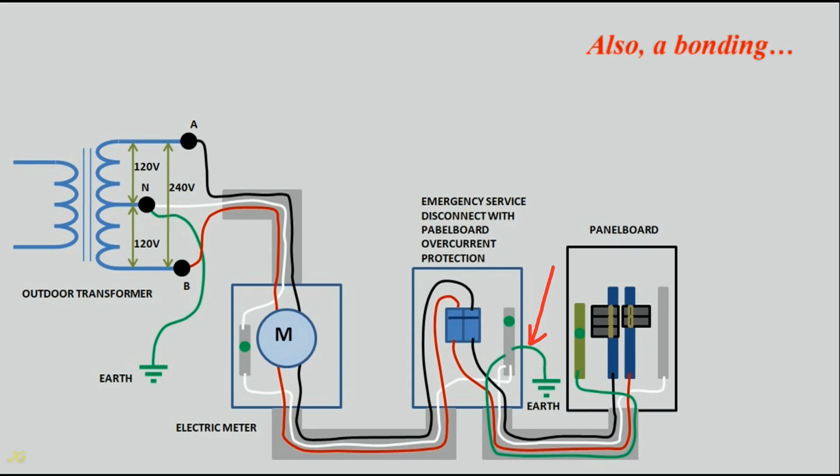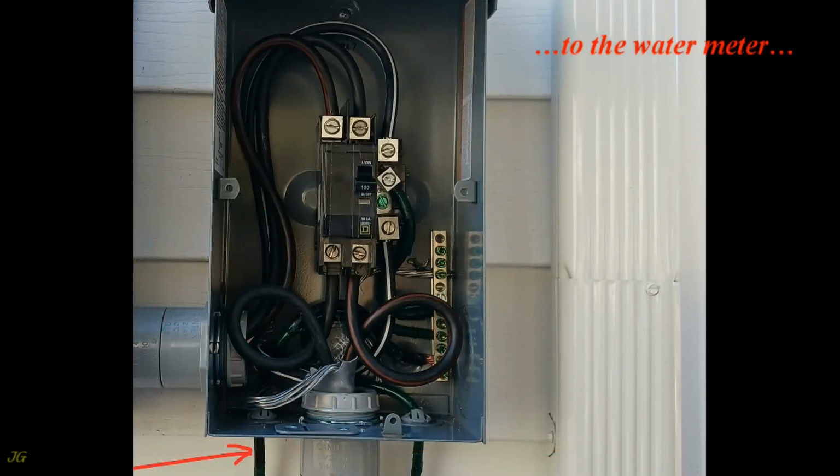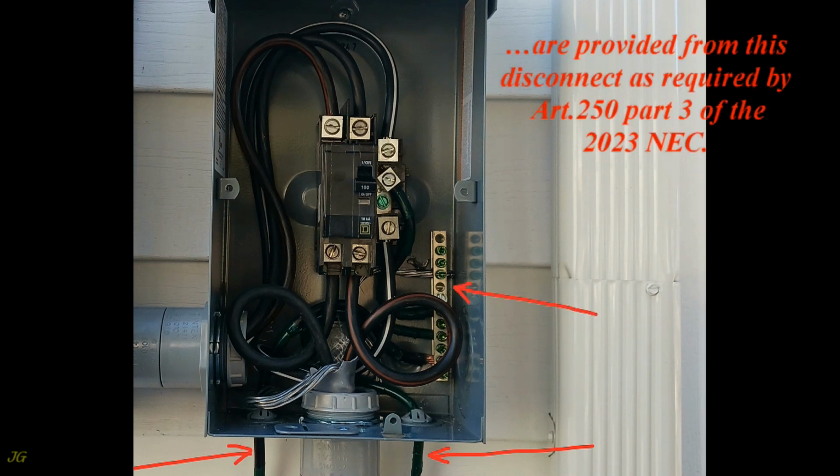Also, bonding to the water meter and to the ground rods are provided from this disconnect as required by Article 250 Part 3 of the 2023 NEC.